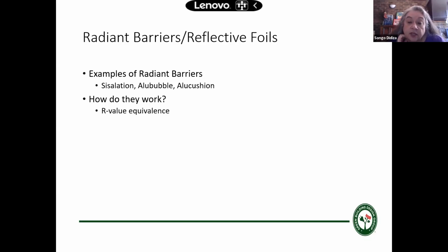So the manufacturers would have to measure what that is, or the designers, the professionals, would have to get hold of those numbers and say, I'm now going to add that damp-proof membrane to the R value addition, but they must have proof of what that R value is. They can't just guess what it is. If you look at it, it's got thickness, it's got some insulating property. It may add to the performance of the roof, but again, you need to know what that number is, and have it tested.